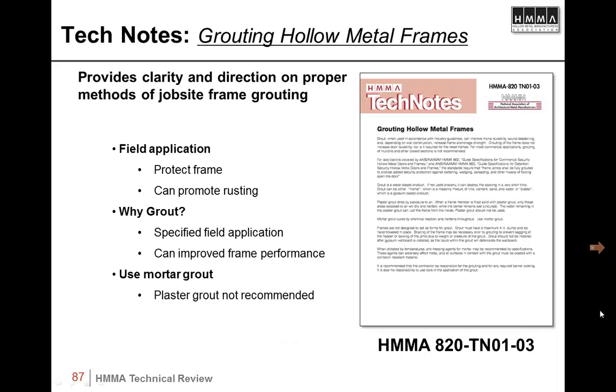Grouting of hollow metal frames, this is a critical tech note, and there are problems related to grouting, and this was developed to give guidance to distribution and anybody ordering or using the product to work with your contractors to make sure that the proper application is achieved. There's description of why grouting is added, and it's not a requirement for fire rating or anything. There is clear definition of the type of grout used or required, and if the proper grout is not used, the proper back coating is not applied or specified, the frames are going to rot out very quickly. And this gives you guidelines for your contractors as to what they should do.